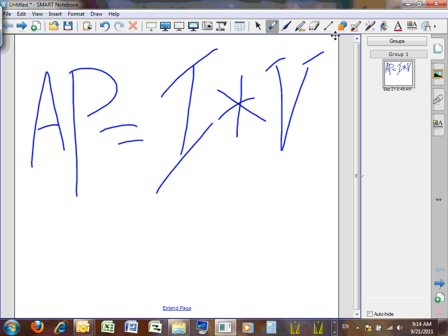When you start sizing for me, when you size the circuit, Rob, you came up with a 20 amp circuit for all your receptacles. Based on what? KW or volt amp? Volt amps. We size transformers based on volt amps. We size conduits and wires and circuit breakers based on the volt amp phenomenon, not the KW.